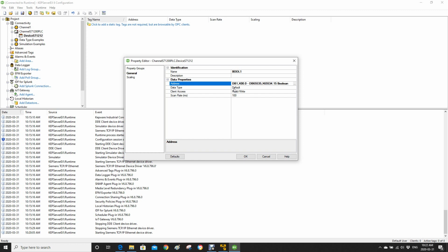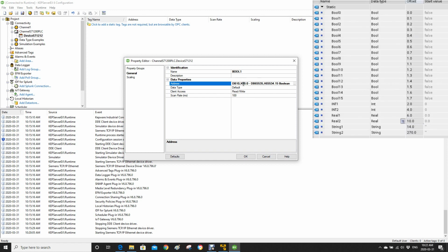So we will use this structure or syntax. But actually our DB number is DB10, if we recall. So we will write this DB10. And the Bool1 address is 0.1. So I will rewrite this 0.1. This is the actual bool address. So I will delete the others. And from here, the data type for this bool is boolean.